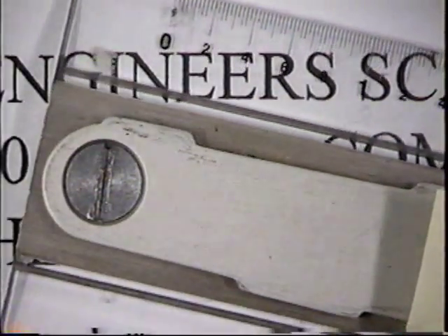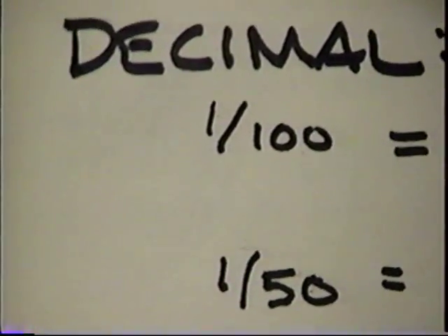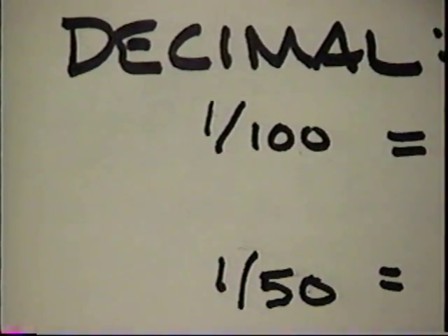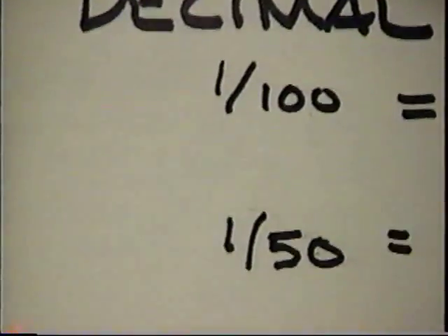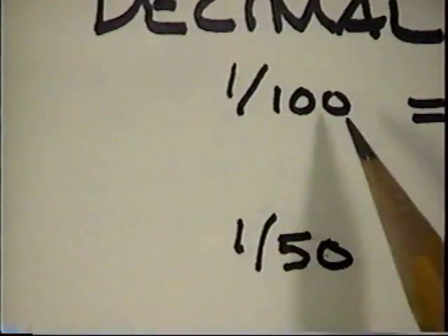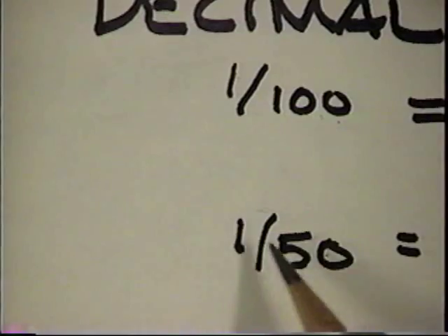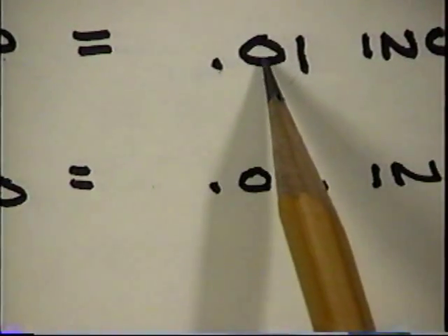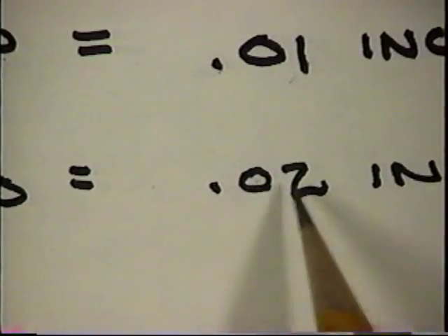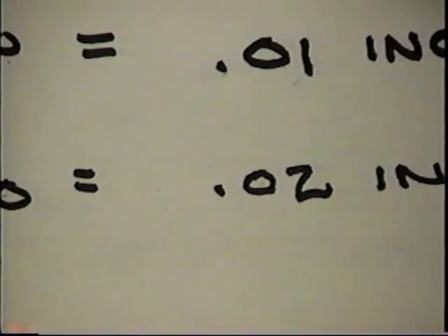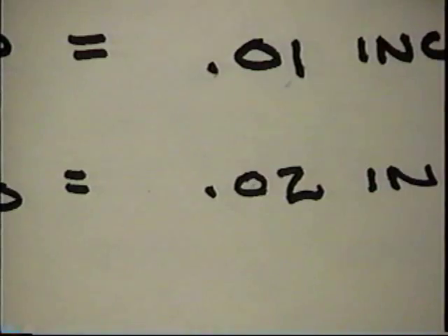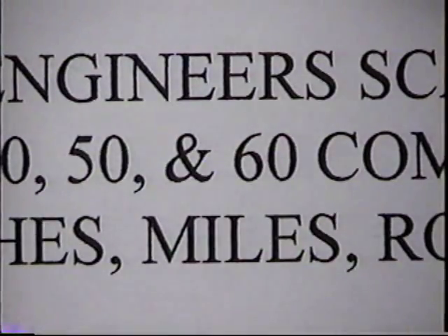So that's our decimal inch scale. And our decimal scale is always in decimals. We can take the unit divided by the number of marks, and we can come in then and work with two-place values, and two-place values are very common when we work with the decimal inch scales and the decimal inch measurements.